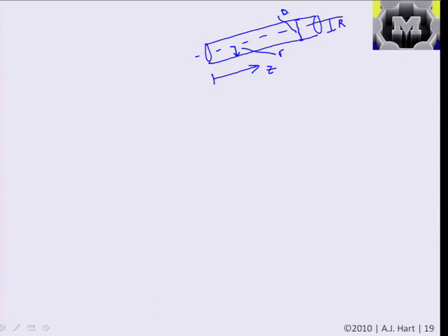And we're going to assume that we have the case of steady, fully developed flow. Which means, importantly for us, that the pressure gradient, dP dz, is constant. So we're not considering any transients or changes in the conditions here. And we'll have this nice parabolic, azimuthally symmetric in the theta direction, velocity distribution. And we're basically going to solve what this is depending on how much slip we have at the wall.